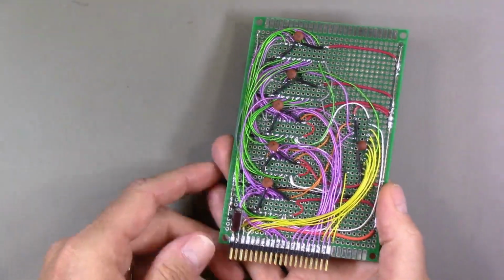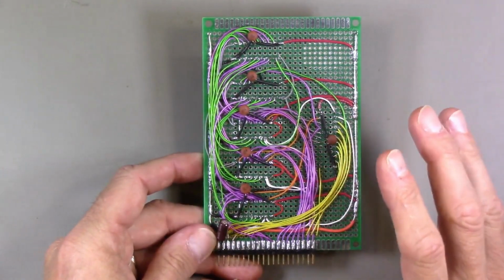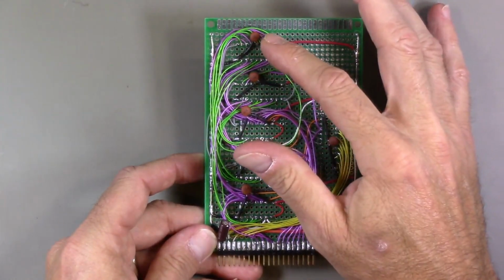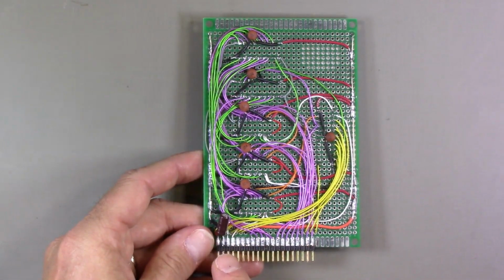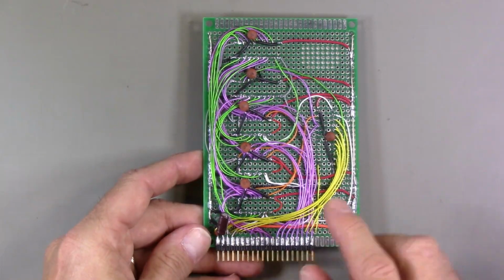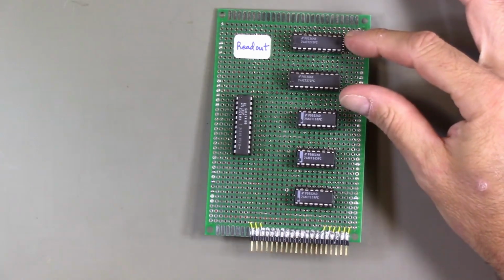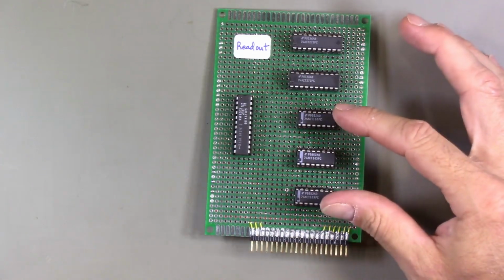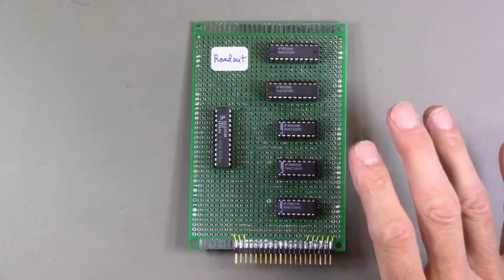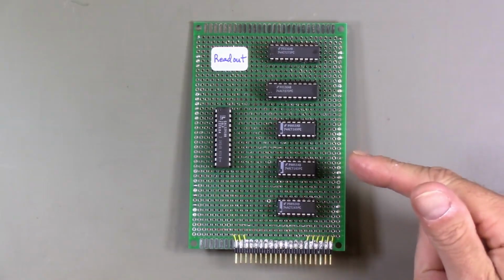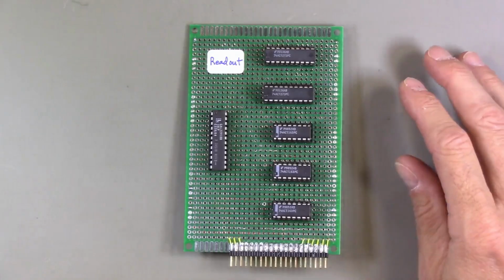I have tried as well as I can to do good decoupling of the power rails. So each IC has a 100 nanofarad decoupling capacitor. I also have a 10 microfarad bulk decoupling capacitor for the VCC and ground here. Here's the control GAL. Here are the ICs for the row begin address. These are the load 12 bits of the readout address. Okay, so let's go ahead and try to do some experiments to see if this thing actually works and if it generates a reasonable series of addresses that can be sent to the VRAM.